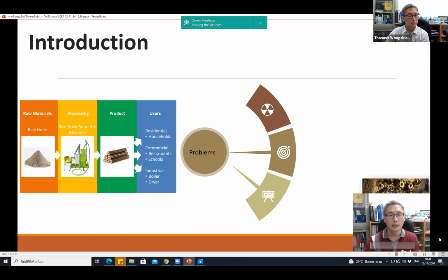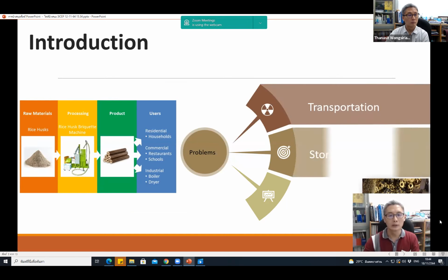The characteristic of increased density may improve transportation, cost management, and storage, since the material requires a smaller volume, making it more compact and easier to use. Briquettes from agricultural residue are of interest and are used for residential and industrial heating, including applications in many industries. There are three primary techniques for increasing density: high and medium pressure with heating, and low pressure using a binder.